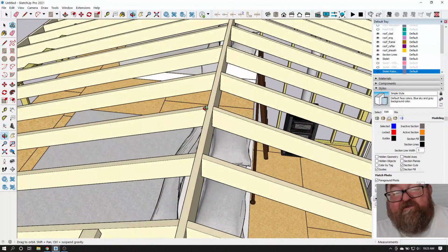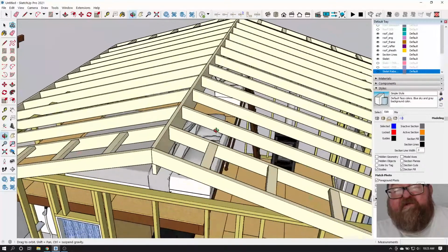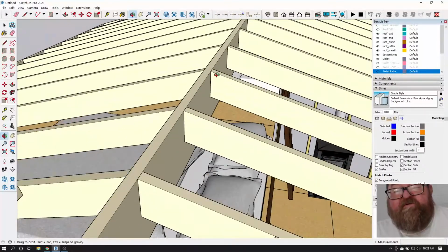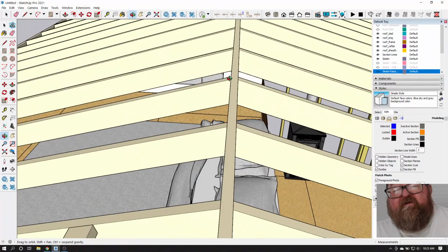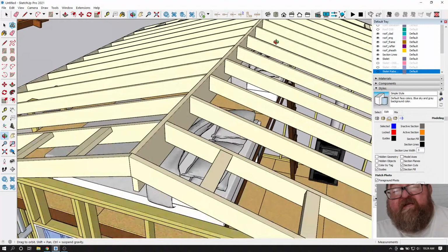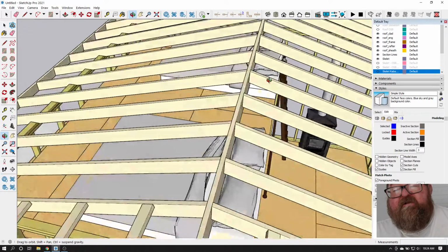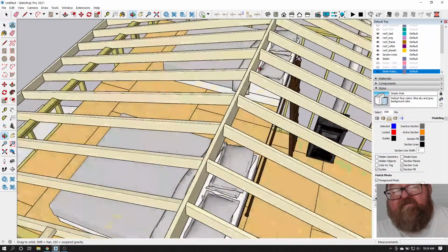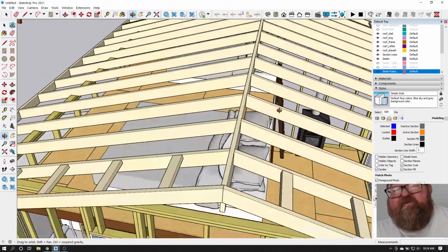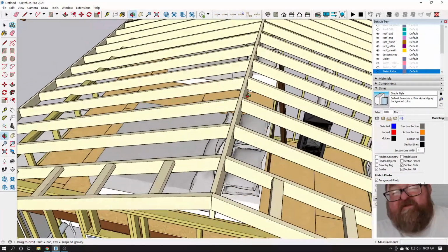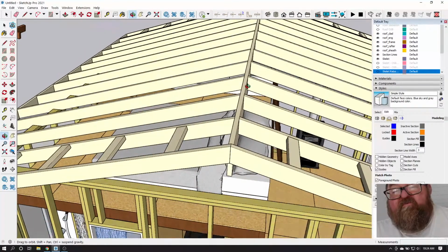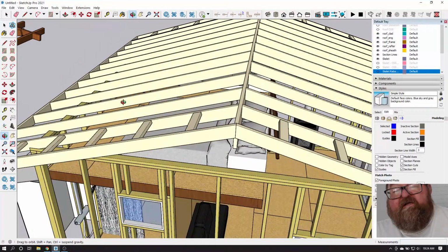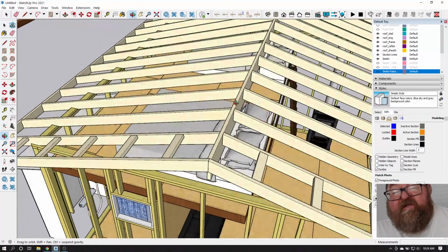The rafters would just be nailed together at the top. I've renovated some 100-year-old houses where the rafters just met each other, and then they had wood decking that kept them all separated on the spacing they were supposed to be on. So the ridge board is not structural when you have collar ties and ceiling joists, but you can make it.